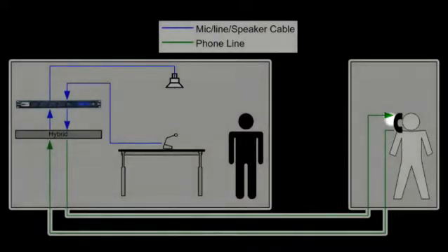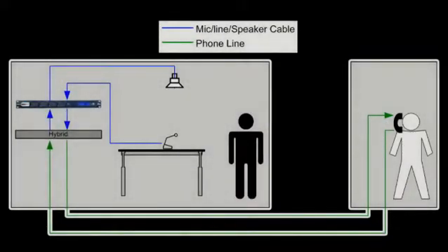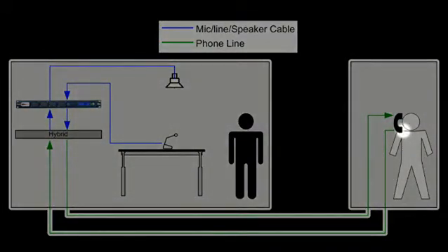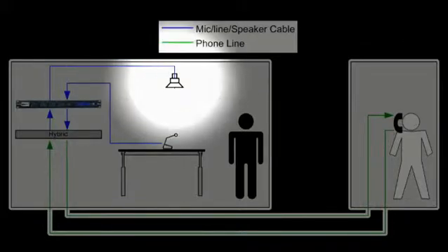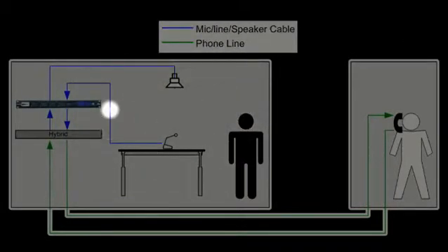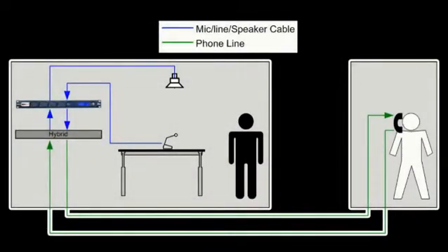Fortunately, BSS Audio's new AEC input card provides a perfect solution to this problem. While the sophisticated processes by which echo is removed are beyond the scope of this video, the fundamental goal of AEC can be stated simply: to prevent any far side speech from returning to the far side. While the far side receives the primary benefits associated with the AEC input card, the near side also indirectly benefits from the overall improvement in communication during calls. In addition to echo cancellation, the AEC input card also provides powerful features such as noise cancellation and automatic gain control. These features will also be demonstrated during this video.